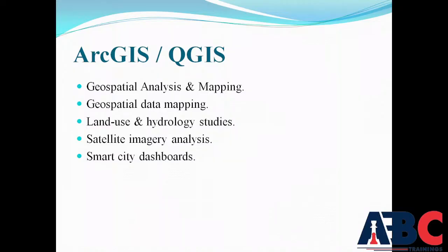Next one is about the satellite imagery analysis. ArcGIS supports high resolution satellite and drone imagery for powerful spatial insights. Image classifications such as urban, vegetation, water bodies, change detection before and after any analysis, terrain extractions like DEM or DSM creation, monitoring construction progress using time series imagery. This helps in site selection, environmental modeling, and urban planning.